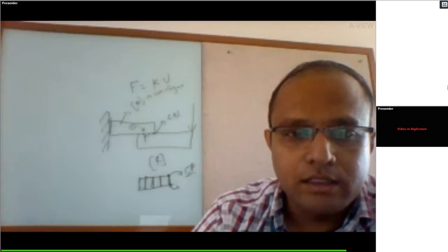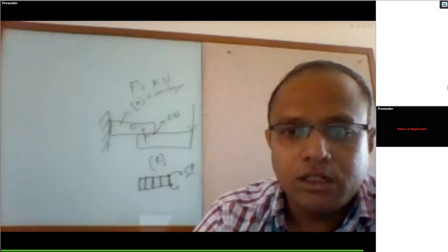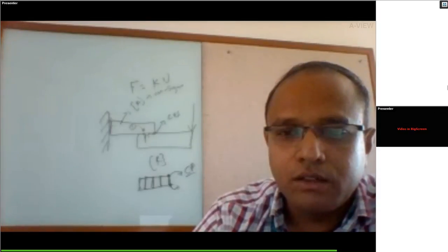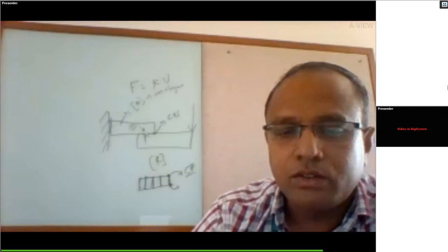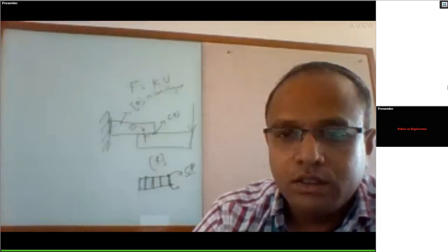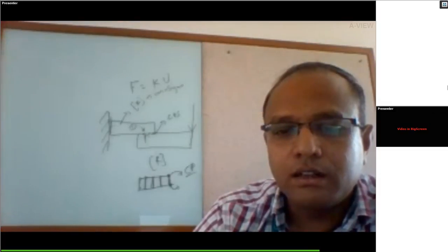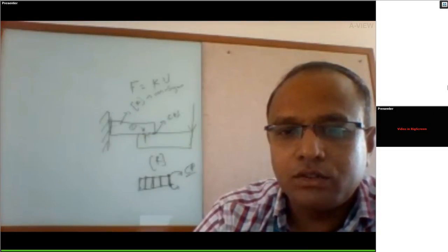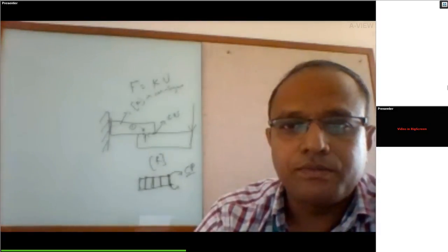This is our 360 degrees model. Instead of solving 360 degrees, we can take a simple sector model and enforce the symmetry by coupling at the cut faces. All the nodes at the cut face need to be rotated into a cylindrical coordinate system, and then these cut face nodes need to be coupled in 3 degrees of freedom.